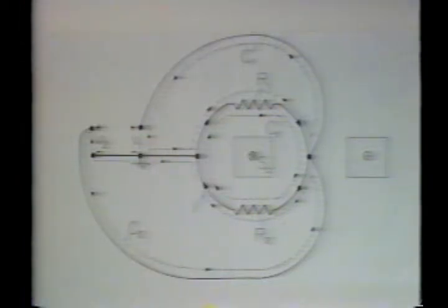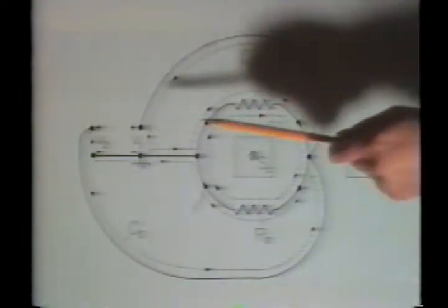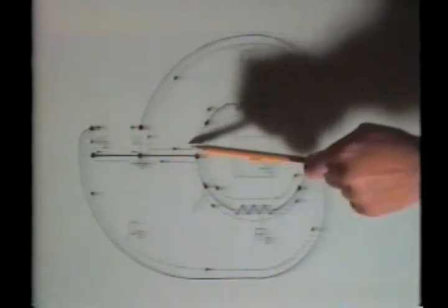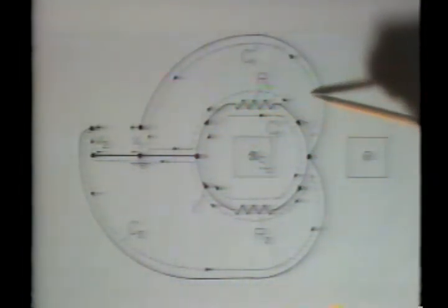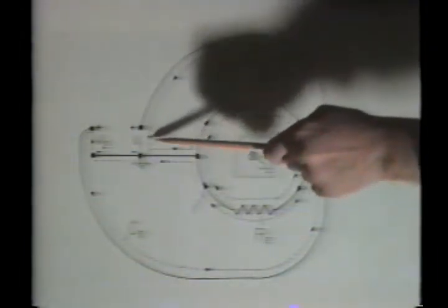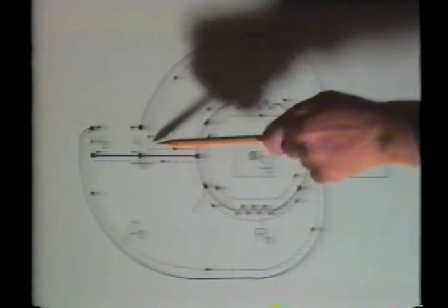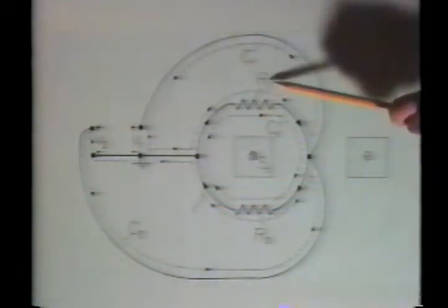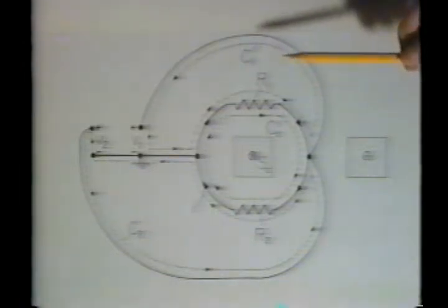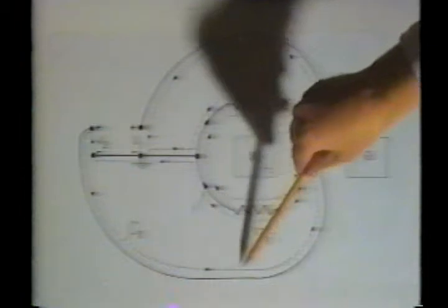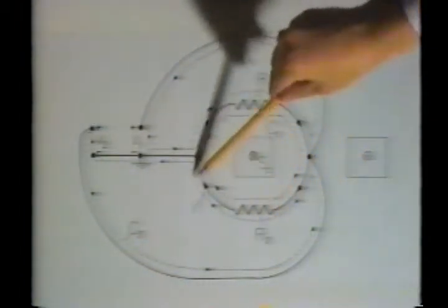The current out of the positive terminal of R sub 1 is that into the positive terminal of R sub 2. When voltage 1 is positive, voltage 2 must be negative. The ratio of the voltages is the negative ratio of the resistances. In our case, the ratio of the resistances is 30 ohms to 10 ohms, 3, just as we measured.